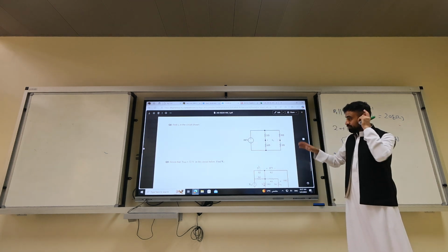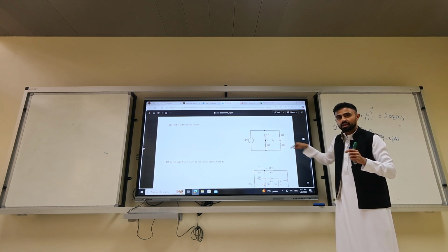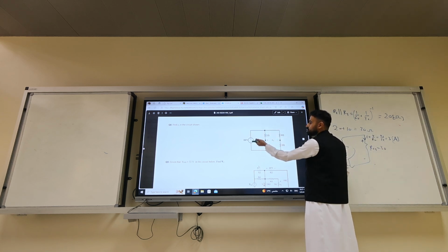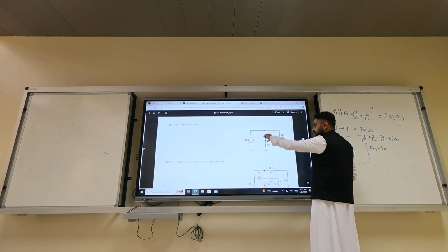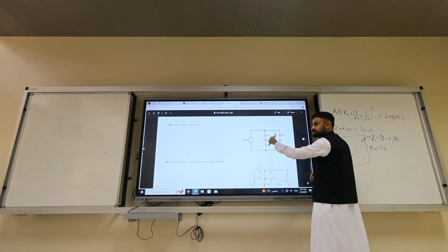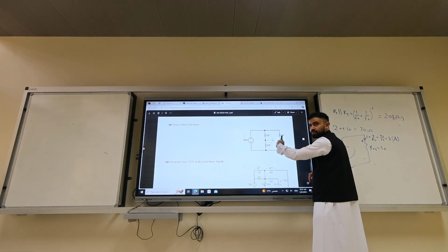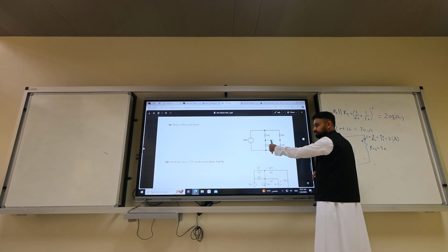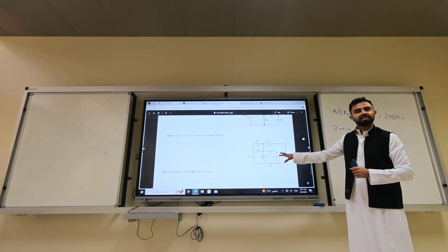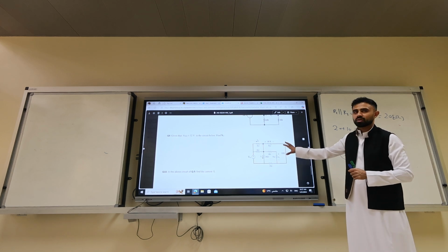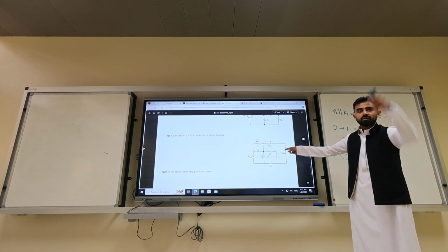So the question is, if he gives you Vx, keep it as it is. He didn't give you what's the voltage drop across 6 and 3, so you assign it based on the current. So you will say the current here will split here and there. And then the current that goes here is going to be plus minus, plus minus. And then you do a KVL around half a loop. You can do a KVL here. And then you can calculate the answer. Get it? Again, this question takes effort. Try to solve it. But there is a trick to solve it. I didn't solve it. Maybe come to the office hours, we can talk about it. Get it? Come to the office hours. Okay?